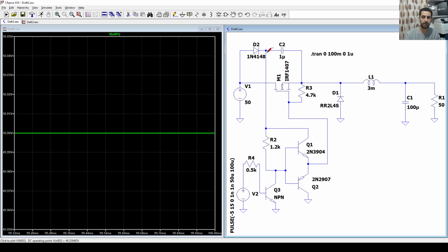So that transistor here, we brought it here because we want to make everything referenced to this voltage. Okay, so that voltage will supply this configuration, and also supply the base once we turn off that one. So that one, once turned on, brings that point to the ground and turns off that point, and will turn off that MOSFET.